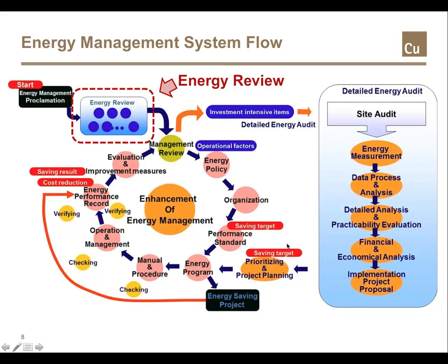Once the first management review confirms the energy performance indicators and the energy baseline, an energy program will be authorized that takes action on energy conservation opportunities, or for energy intensive ECOs, it authorizes further study. All authorized actions are documented in an energy management action plan.